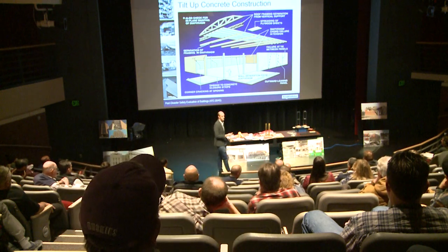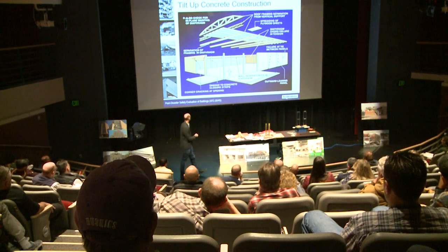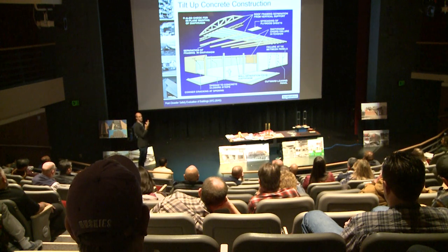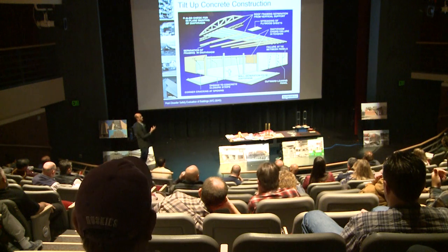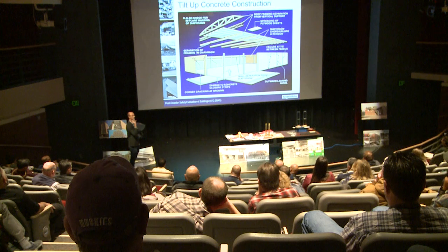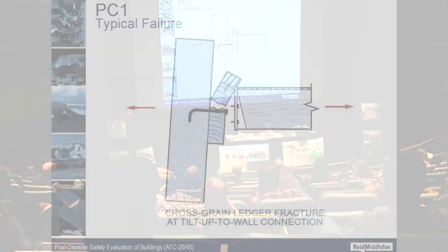And so the isometric view here depicts a couple things to look for. Certainly the walls leaning out of plane, the interface between the walls can be damaged, but predominantly historically the big concern has been separation failure between that connection of the exterior walls falling out of plane, pulling away from the building from the wood framing roof structure.